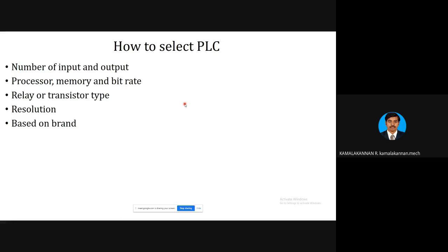Next one is resolution. Resolution means, as I have told you, how small an input it is responding to. So depending upon that you can choose. You can choose the PLC accordingly. Sometimes you can choose for 1 centimeter.